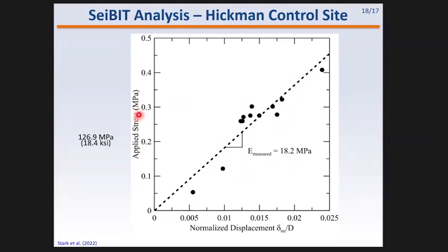So the applied stress comes off the rail strain gauges, and this normalized displacement, here's the tie displacement coming off the cameras, and D is the depth of influence of the load into the track. Because strain is the change or deformation divided by the initial height of the specimen. So we estimated that initial height to be about 8 inches.